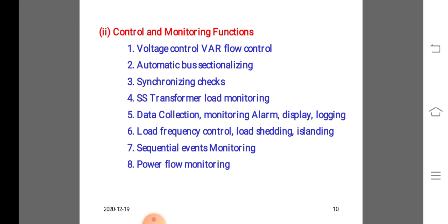The earlier form of signal circuit used for SCADA telemetry consisted of twisted pair wires. Although simple and economic for short distance, it suffered from reliability problems due to breakage, water ingress, and ground potential rise during fault.